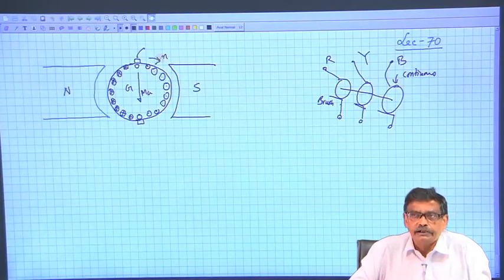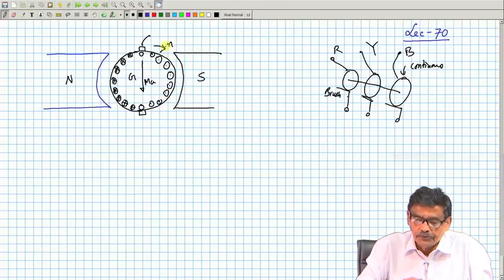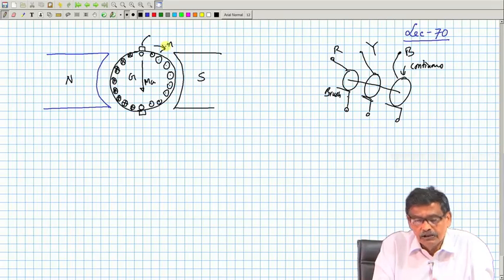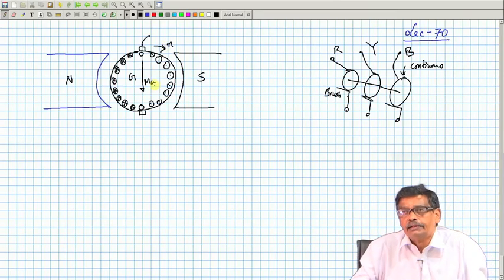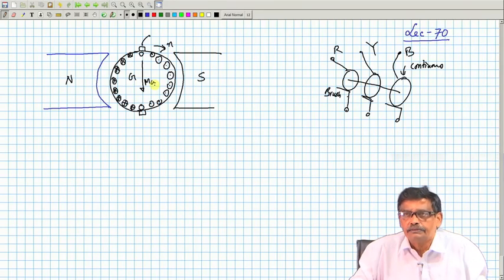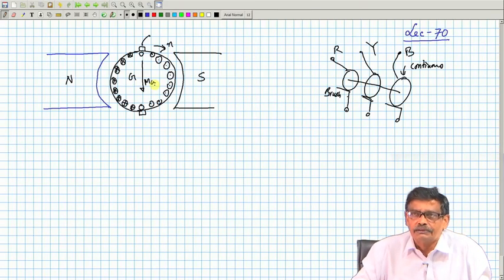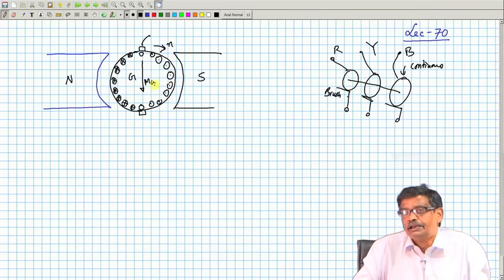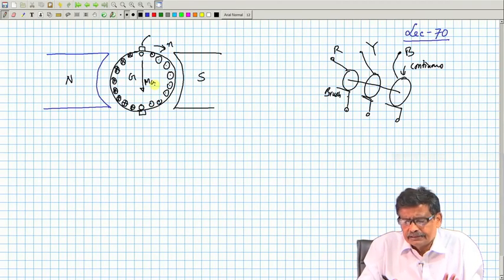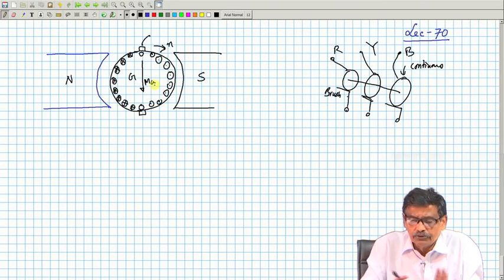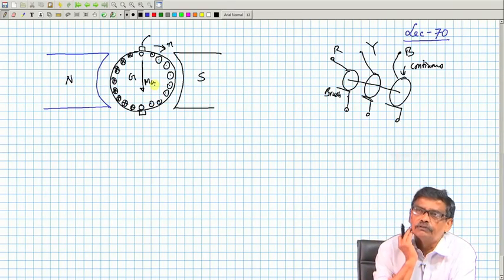So, in a large DC machine, you cannot just have only a field winding and an armature winding and feel happy. No, it is not going to happen. There will be very large flashover. What is to be done then? See, without doing any maths, I want to nullify the effect of armature MMF.